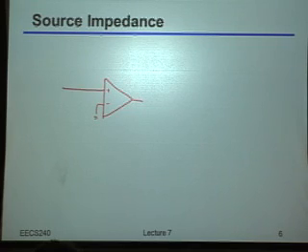It could have input-referred voltage noise, let's call that V_in squared, or also input-referred current noise, let's call that I_in squared. In that previous example, we could even have taken an amplifier with quote-unquote voltage noise and changed it into something with current noise just by tying that transimpedance feedback around it.